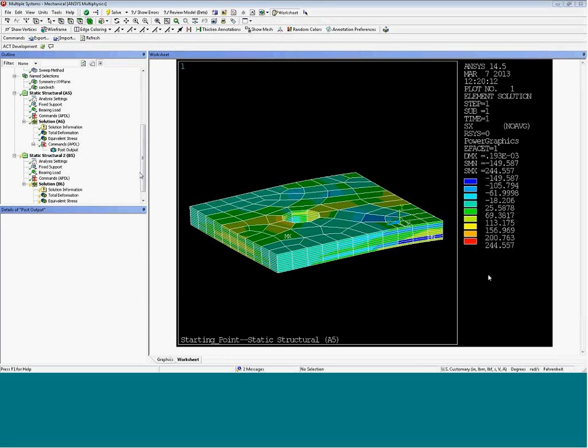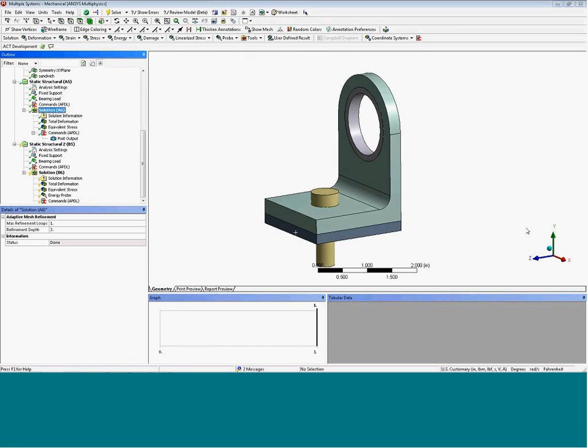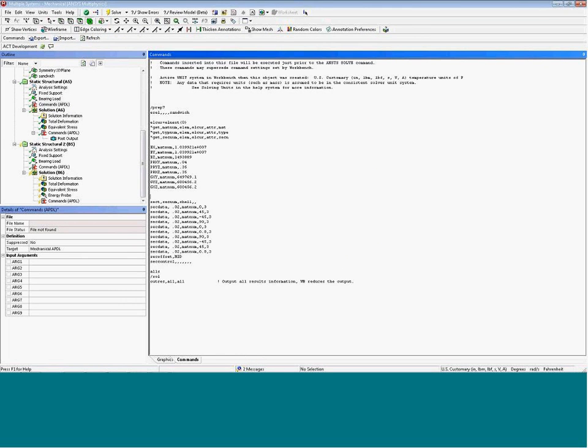All right, so let me go back and show you a couple more things we can do with the command blocks. The next thing to do is this command here where I define the section properties. These are the ANSYS commands for putting in a bunch of different layers, each that amount thick, and then there's a whole bunch of layers. So what if we change the geometry? We'd want these thicknesses to update when we did that.